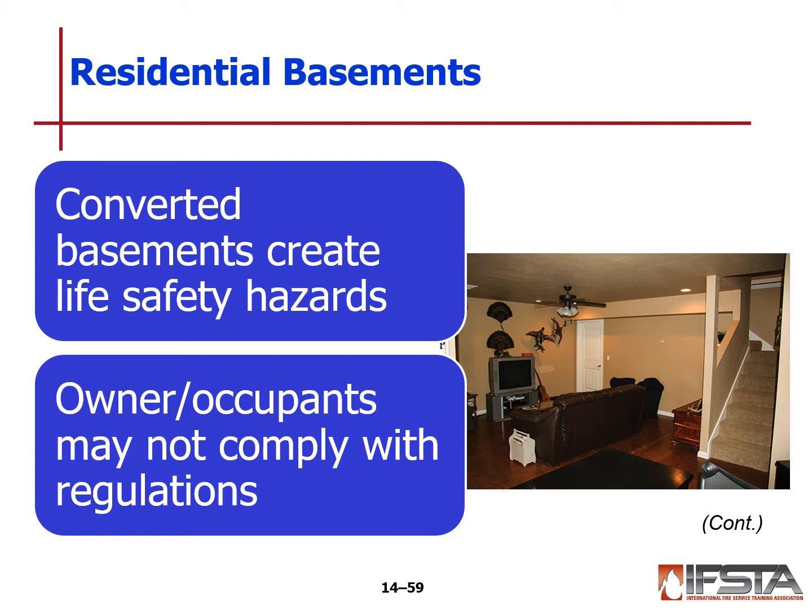Converted basements create life safety hazards. Owners and occupants may not comply with the regulations when they do this. A lot of times the basement will, in the initial construction phase, not be finished, and then later on folks will go back and finish their basement, and sometimes owners and occupants do not get proper building permits. They'll go ahead and do this on their own. Maybe they're doing their own electric, their own sheeting with drywall and things like that. And so what we don't know is, was it done to code and properly?